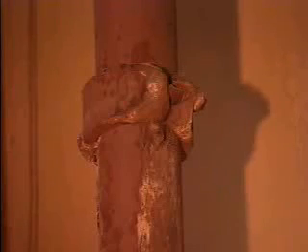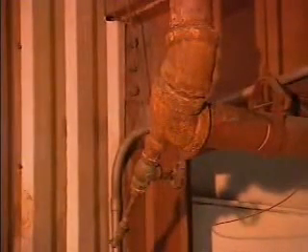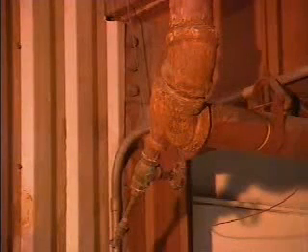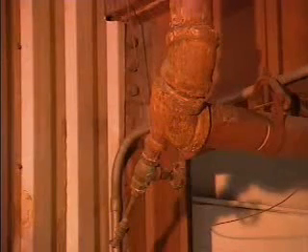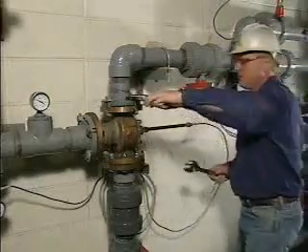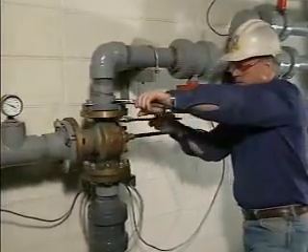Corrosion can be either external or internal. External corrosion occurs when a condensation of moisture from the air or another source forms on the outside of a pipe. This makes the pipe appear to sweat. Over time, this moisture causes corrosion, which wears the metal away. Any dripping liquid can cause external corrosion as well. To stop continued external corrosion, the source of moisture causing the corrosion must be identified and eliminated.